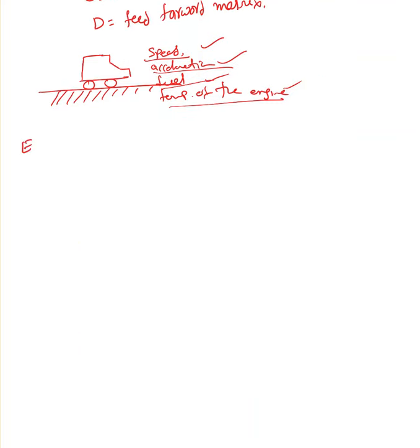Here is a simple example. We're going to find the state equation and output equation for the given circuit. The number of state variables in an electrical circuit always depends upon the number of energy storage elements. Here I have one energy storage element, so we're going to end up with one state variable. U is the input, Y is the output, with R and L. We're asked to write down the state equation and output equation, and we're going to solve this in the time domain.